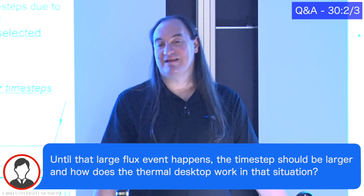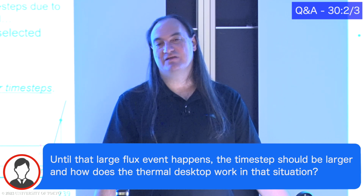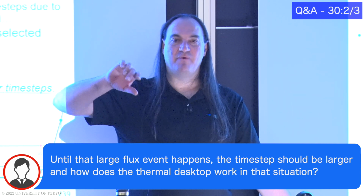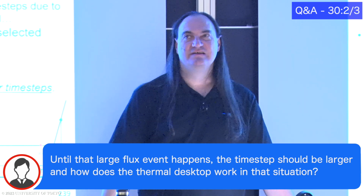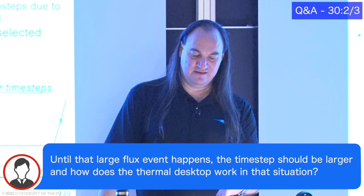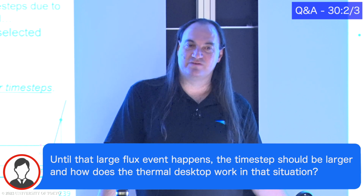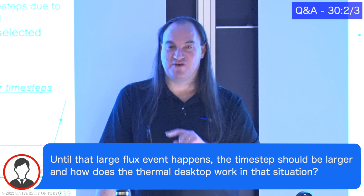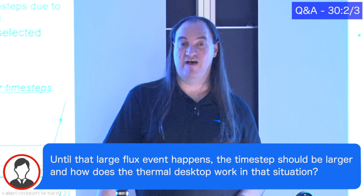Well, are you talking about the automatic time step calculation? Yes. Yeah, I don't fully understand how their automatic time step calculation works. I think it's looking at 4 different points and trying to extrapolate from that what the optimum time step needs to be. I've just found that by and large, unless I've been really careful with the model and don't have the things that drive the CSG to a small number, I just end up having to wait forever for it to solve, rather than saying, hey, you know what? I'm smarter than you are, use 30 seconds, don't use what numerically is an optimum value.